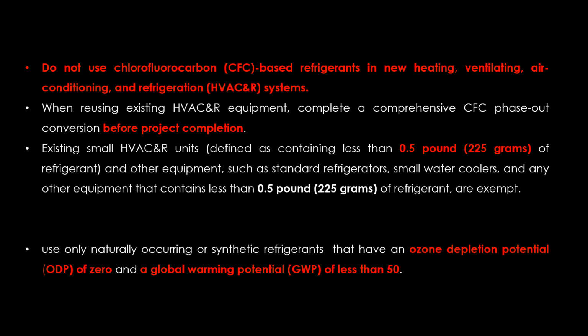We are not supposed to use CFC based refrigerant in new heating, ventilating and air conditioning and refrigeration, that is HVAC and R system. Another case, if you are using the existing HVAC and R equipment, we need to do one thing: complete a comprehensive CFC phase out conversion before project completion. So the term before project completion is very important, not after 2 months or 3 months, just before the project